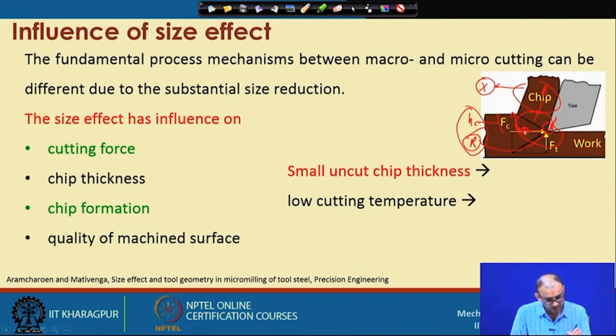So, this material becomes a little bit soft, and when this soft material comes into contact with the tool, your tool need not give more force to cut it. That is the advantage of having a higher uncut chip thickness, but that is not happening here. So, our cutting temperature is very low, and it will not help in removal of the material by softening the part.